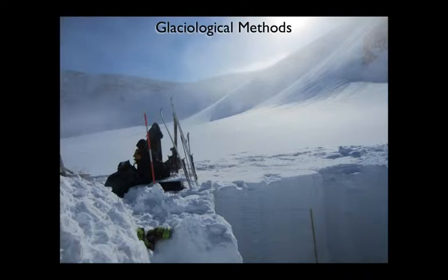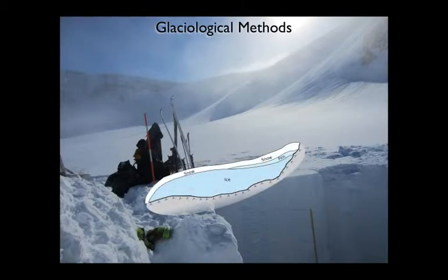The glaciological method sums year by year the mass added in the accumulation area and the mass subtracted in the ablation area. We may start by measuring the accumulated snow. This, as mentioned previously, is done by probing snow depth and measuring snow density. We then measure the amount of snow and ice removed during the ablation. By measuring total accumulation and ablation, we can calculate the amount of water that the glacier contributes to stream flow.